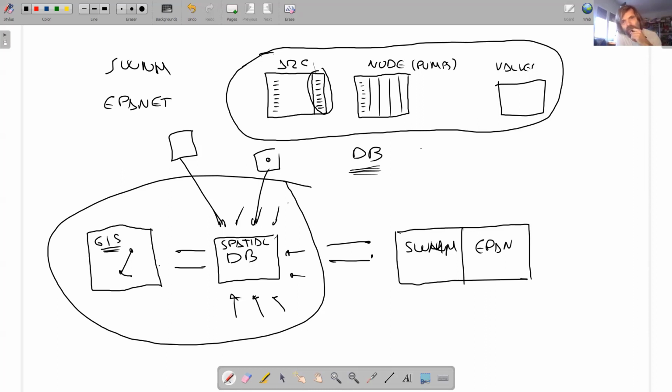Okay, and there were, for example, the constraints. Constraints said, okay, you cannot define an arc, you cannot define a pipe if there is not one node at the beginning and one node at the end. So databases include in native form something that we call constraints. Constraints fix some limits of what you can do in the database. So if you create this data structure based on tables and you create the constraints, you have an extremely reliable system. You cannot break your network, because the constraints don't let you. You cannot delete a manhole that is involved in a pipeline. So constraints were a second crucial point.